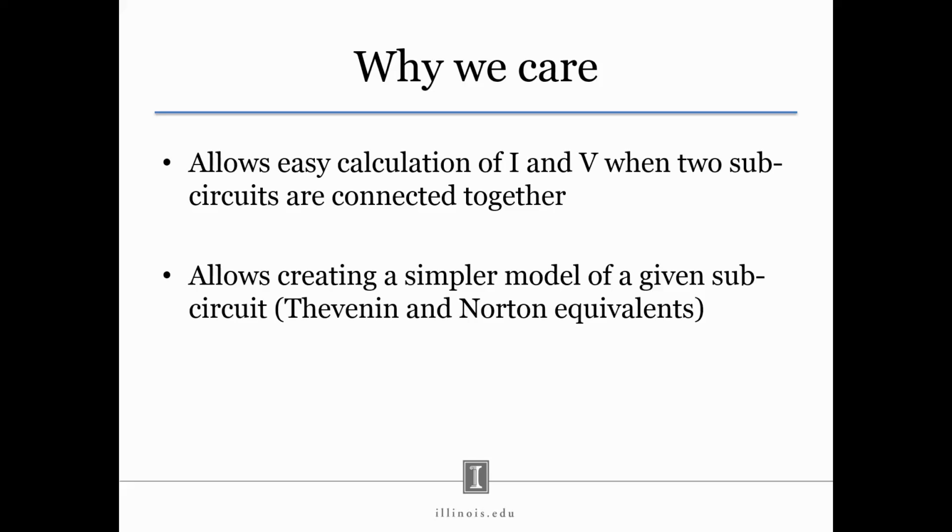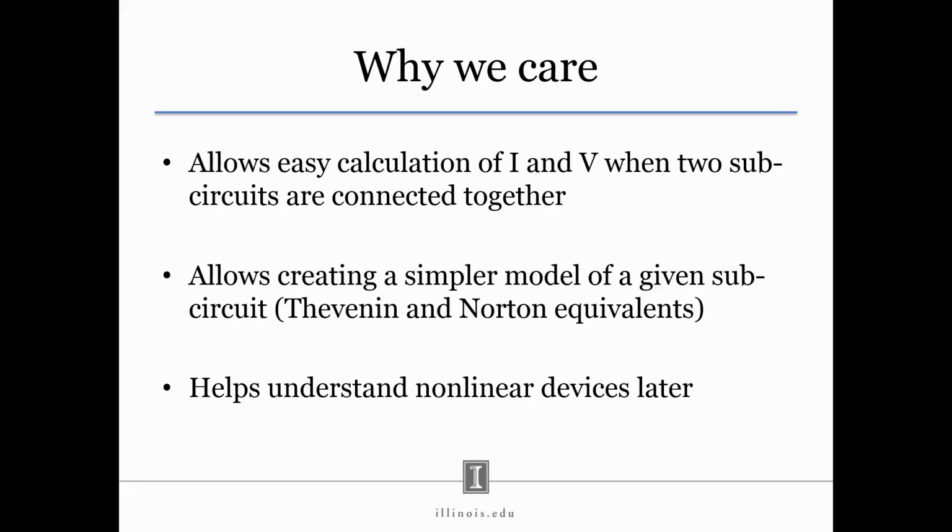Also, it can allow creating a simpler model for a given subcircuit, or if you don't know anything about the subcircuit, you can measure it and create a simple model. And those are going to be called Thevenin and Norton equivalents, and we will talk more about it on Monday. This kind of analysis will help you understand nonlinear devices later, because some regions of nonlinear devices can behave fairly linear, and then you can model them as sources and resistors.